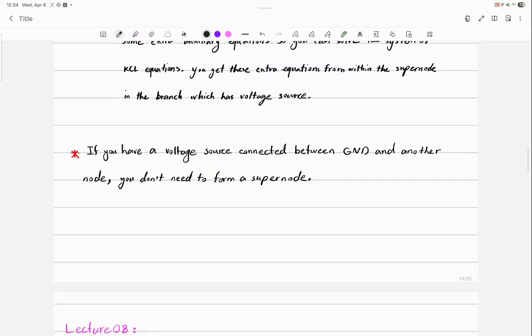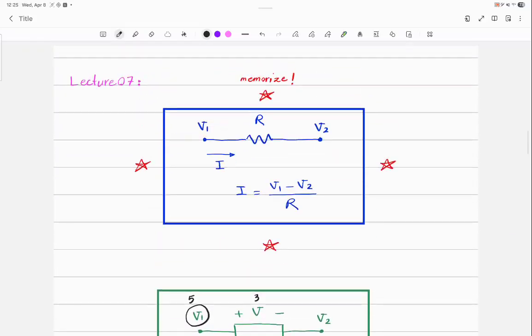How do we do nodal analysis? First, open the box of the highlighters that you have, okay? Use the colors, identify the nodes. A ground, you need a ground. Then label the nodes. I recommend using your own labels. Do not get confused by the labels already printed on the circuit. Okay, use your own labels. Then you write KCL at each node using the blue box.